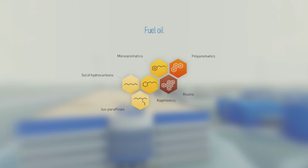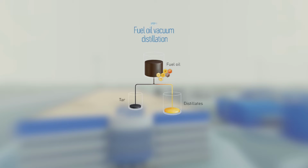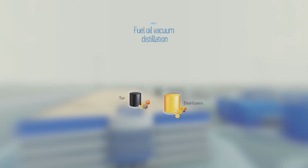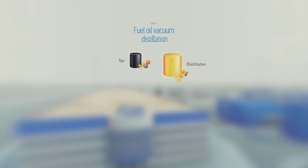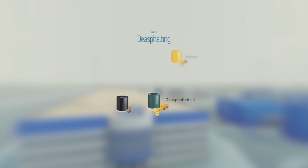Base oil production is the starting point in the manufacture process of final lubricants. Oil distillates and tar are supplied from vacuum distillation unit of Omsk refinery plant to the lubricants plant. Tar is pumped to the deasphaltization unit for production of base oils.